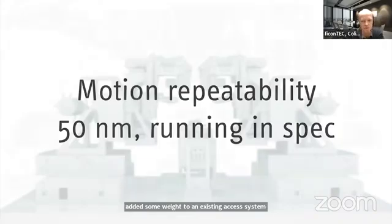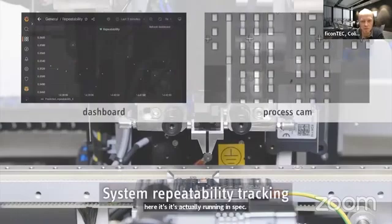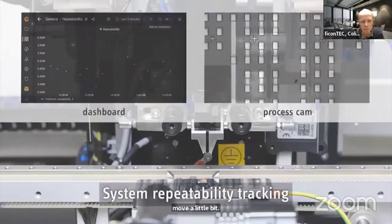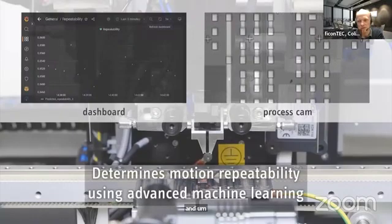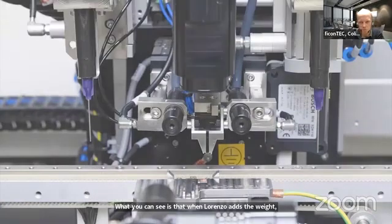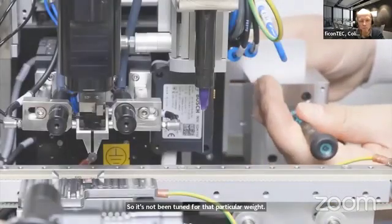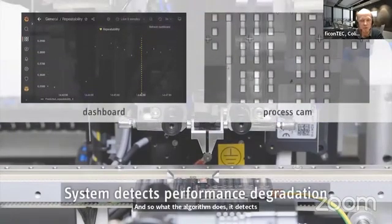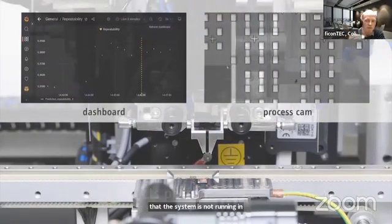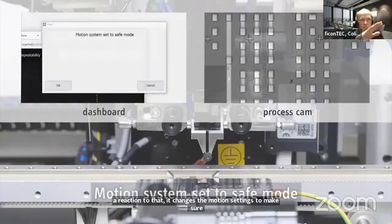So here it's actually running in spec, and we move a little bit back and forth. And what you can see is that when Lorenzo adds the weight, the motion system is compromised. So it's not been tuned for that particular weight. And so what the algorithm does, it detects that the system is not running in spec anymore. As a reaction to that, it changes the motion settings to make sure that it runs in spec after that.